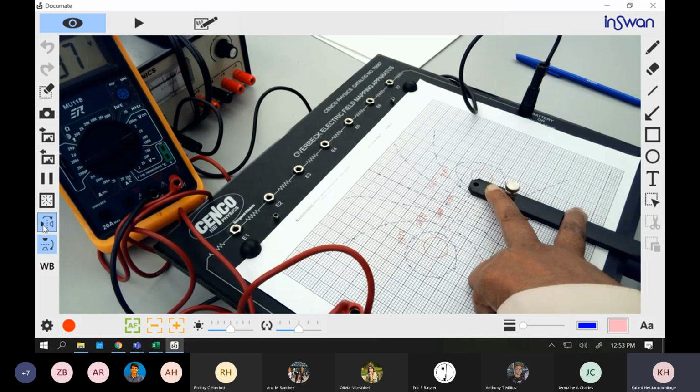Good. So now we need the voltage of the two electrodes. We supply around 10 volt, but that 10 may not exist here because it can reduce due to some resistance in the process. Because of that, you take the black probe out and connect it to the other end of the table. That will give you the total voltage of your two terminals. So I have 9.47. You should have something close to that. I'm going to write that number on top, 9.47 volt.